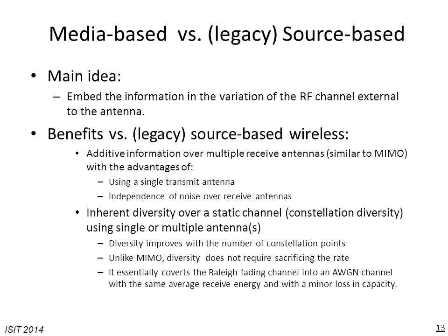So if I have, for example, 4 receive antennas, corresponding to each bit pattern at the transmitter I will have 8 IID components with Gaussian distribution at the receiver, corresponding to I and Q of those 4 antennas. And the important point is that the distribution of the constellation points will be IID Gaussian. The fact that they are independent of each other brings the property that the information received over those separated receive antennas will add together.